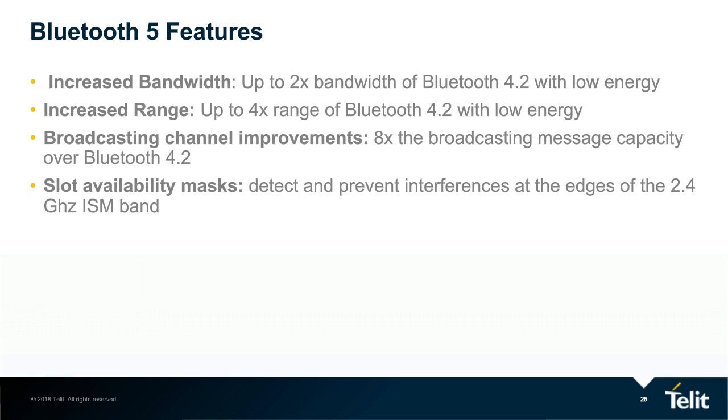In the real world, if you look at our embedded modules, we can achieve from module to module about 500 kilobits per second currently with the 1 megabit PHY. Just for your information, under iOS, this is halved. It's not because we perform worse, but because iOS does not allow us to go faster, imposing its own settings. So we expect this to double for sure.